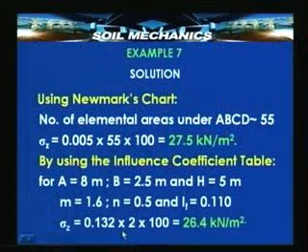So, this gives us m is equal to 1.6, n equal to 2.5 by 5, that is 0.5, and corresponding influence factor is 0.110. The stress would be the value that we get corresponding to the influence factor readings, and that into 2 into 100 would give you the stress arising due to the area.